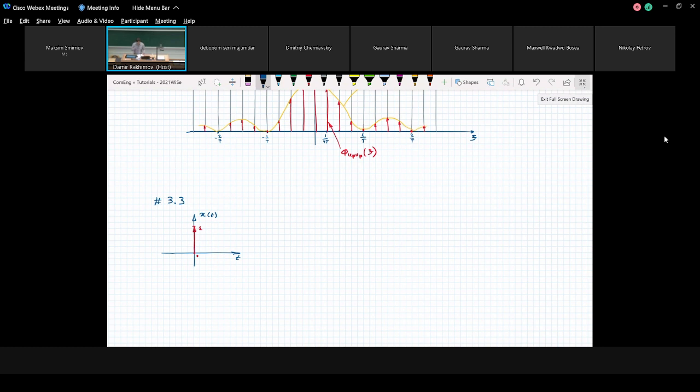We actually have two ways to find it. I will show both options for calculating the correlation function. In the first option, you calculate the correlation function via the spectrum of the delta pulse. As the first step, we go from the time domain to the frequency domain by calculating the Fourier transform.